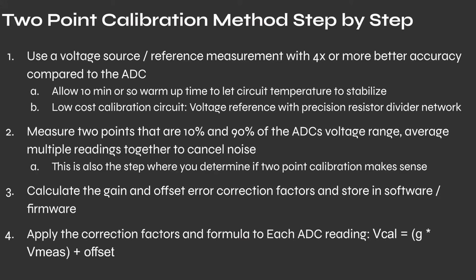Before we get to the demo, let's just step through the process because there are some other things during the process you should be aware of. We want to establish a voltage source or some type of reference measurement to establish what is our actual calibration voltage. So maybe you have a really accurate voltage source, you can feed it right into your ADC, set it for different values. Or maybe you have a stable voltage source that you then can measure with a highly accurate voltmeter to then get your actual voltage value that your ADC is measuring. And that's what I'm going to use in my demo.